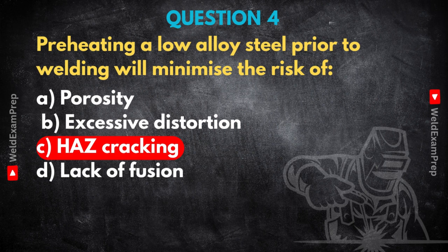Is there a specific temperature or does it vary? What does an inspector check for? Oh, it definitely varies. Depends on the steel's thickness, its specific alloying elements, the welding process. It's all laid out in the WPS. The inspector's job is to verify that the specified minimum preheat temperature is actually achieved, usually using temperature indicating crayons or pyrometers, and that it's maintained during welding.